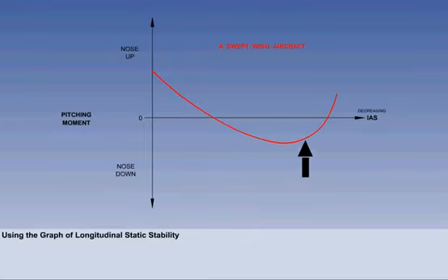From your previous studies of swept wing stall at higher angles of attack, tip stall will begin. And like all swept wing aircraft, this will generate a nose-up pitching moment. In the next segment, we will be using graphs like these to illustrate other variables.